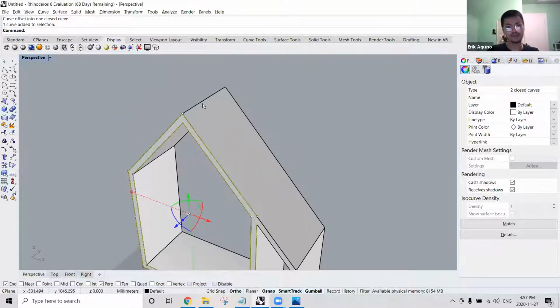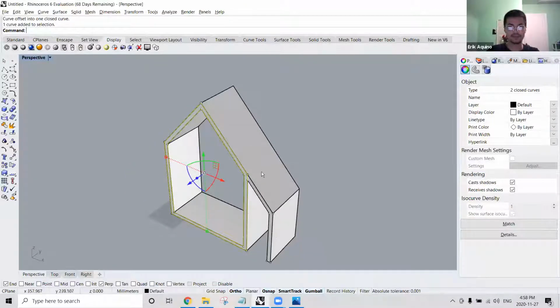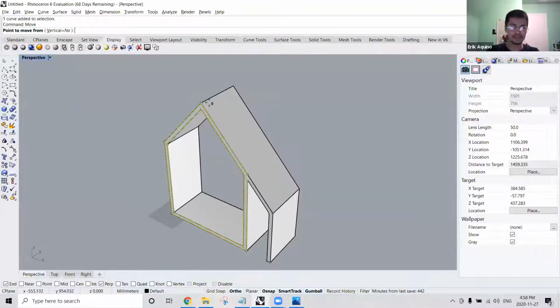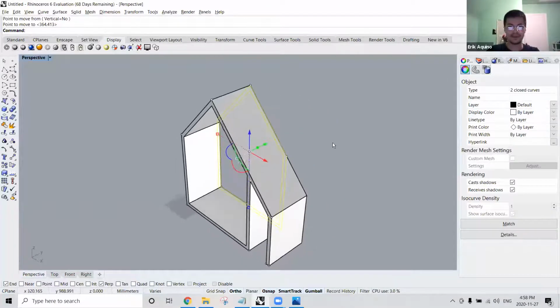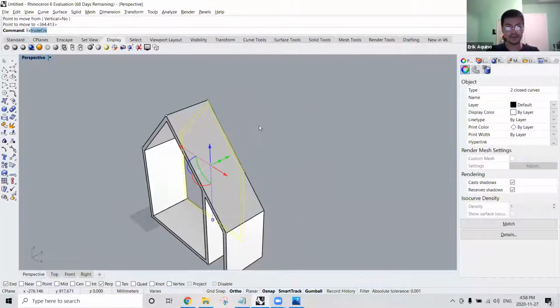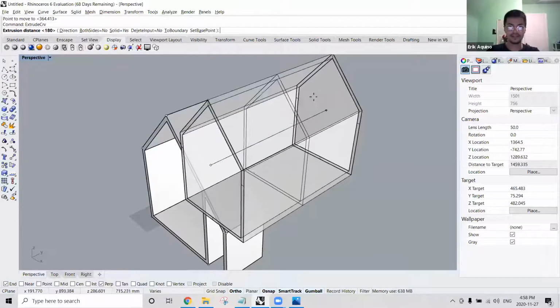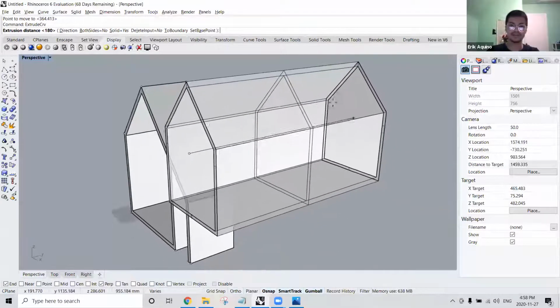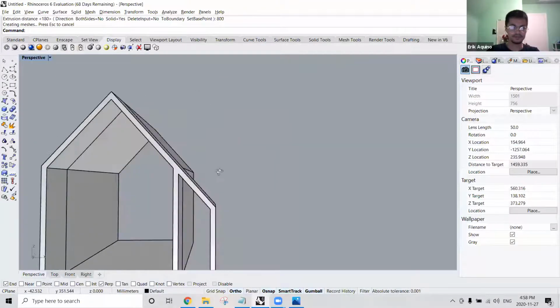And what I'll do is I'll move it to this portion so that it begins after this wall. So I can move this, and because I have my O-snaps on, it's really easy to select this corner and move it to the opposite corner right there. And now that we have it in the correct location, we can extrude our curve again and specify the distance, which looks to be something like this based off the sketch. I don't know. You'll need your dimensions to find that out. So 800 and enter. It's cozy.